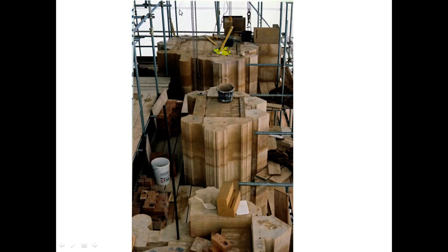column, so these are a series of columns, and of course they are very massive because I remind you again that brick and stone and concrete without any reinforcing have no tensile strength. They're very good in compression. You can push them down very hard, but they will pop, or explode under a huge amount of pressure unless you make them massive enough. So these are massive columns, as were all the great cathedrals in the world, of course.